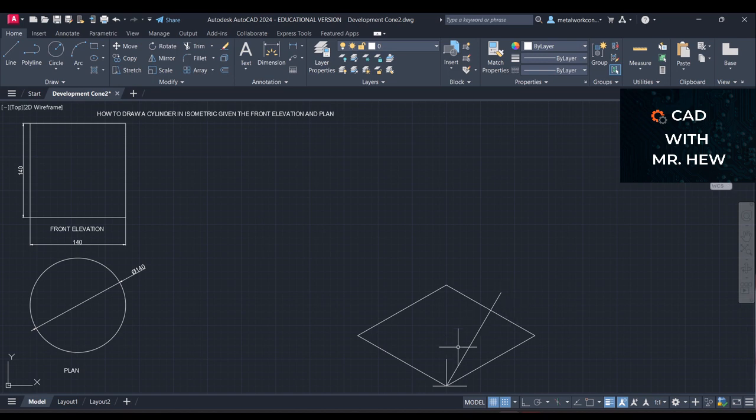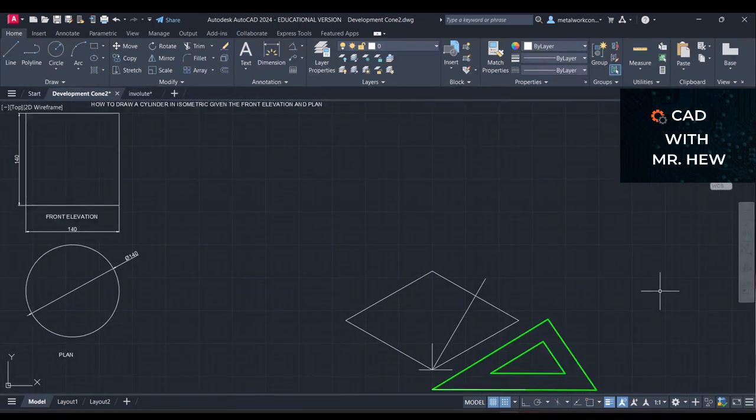So you would take a 60 30 set square and put it at this angle. If you were using drafting equipment, this is how you would get this 30-degree line. You would have the t-square below the green set square, and then you would draw the isometric square using these drafting instruments.